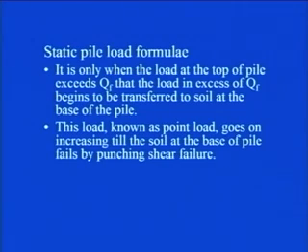It is not that you can go on increasing the load to an infinite extent and the pile can take that load. It has its capacity. So, the frictional capacity you can estimate using that QF. Whatever is your QF, that will be the frictional resistance or the capacity of the pile.